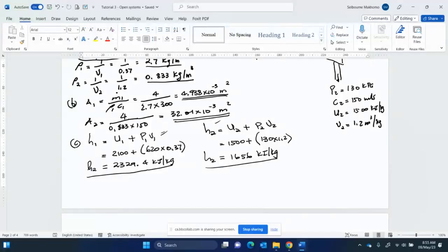Is the pressure. All of these things have to make sense to you. Otherwise, if they don't make sense, that is going to be a problem. So what we have in front of us now, it makes sense for a turbine that the enthalpy at the inlet is H1 here, not H2. I think it's a mistake. Because the steam when it enters is very hot, it makes sense for H1 to be higher than H2.